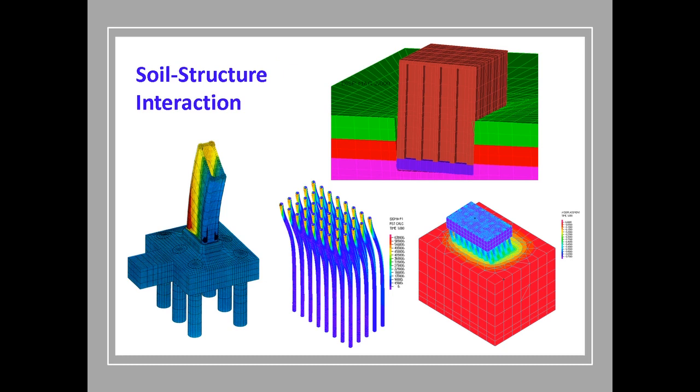The evaluation of foundation behavior and soil structure interaction issues for large caissons and pile cap groups have also been handled using finite element methods. In one example, the finite element method was employed to ensure that the pile groups and cap are capacity-protected members under the seismic design displacement. In another example, it was used to assess rocking of a large caisson under the seismic design ground motion. In a third example, the stresses inside pipe piles under various drift levels were evaluated using the finite element approach.